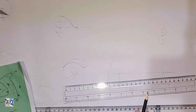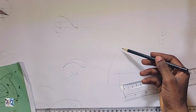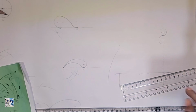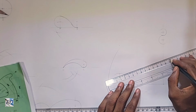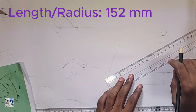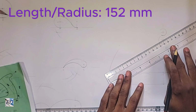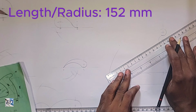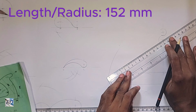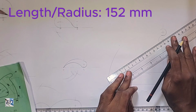So here we use another trick again, and we know that the center has to be on this curve somewhere, right? So we mark out the distance of 152 on our long rule, rather than on the compass. We put that on the center or the point that we want to move from, and then we adjust the rule until we have the zero mark on the arc here and 152 millimeters on the center point.